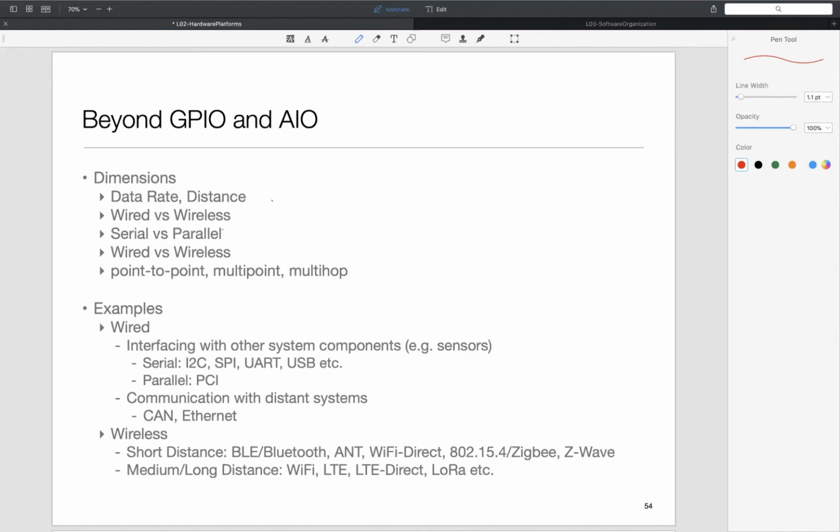You would find on these chips a variety of specialized IO interfaces so that you can talk to devices, and there is a whole ecosystem of devices you can buy which speak these standard interfaces. More common on microcontrollers are the various serial interfaces. You may have heard of terms like I2C, SPI, UART, USB. We all know USB, and there are a whole bunch of others.